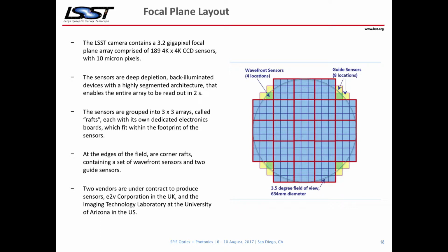And then, of course, we have to align all of these structures together. Given that the system is very fast optically, f/1.2, the tolerances on the mechanical flatness of the overall array are quite tight, and on the flatness of the individual sensors as well. We had to develop new CCD sensors for this project. We've spent a number of years in that development.